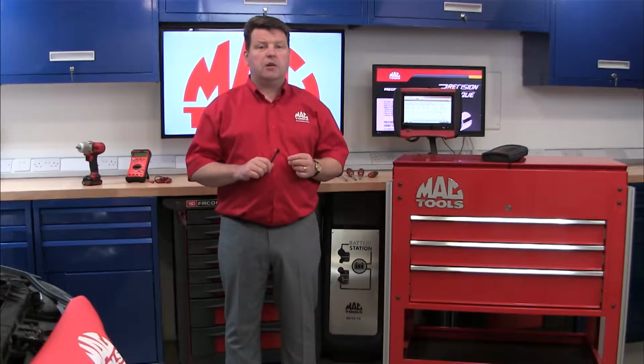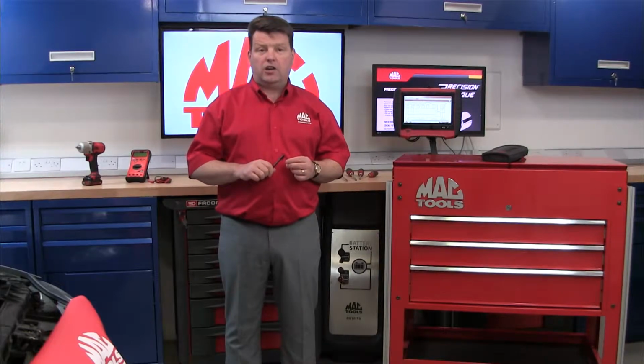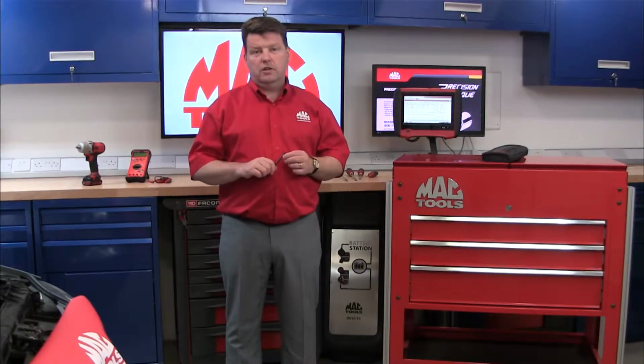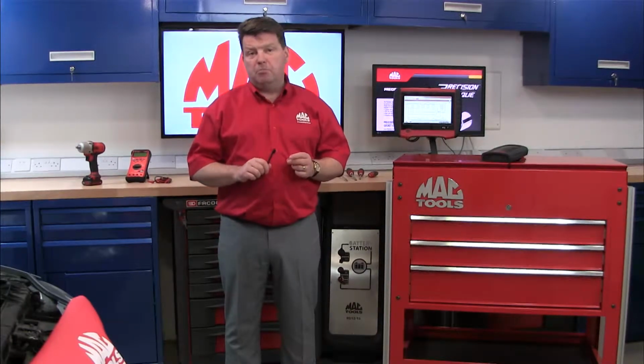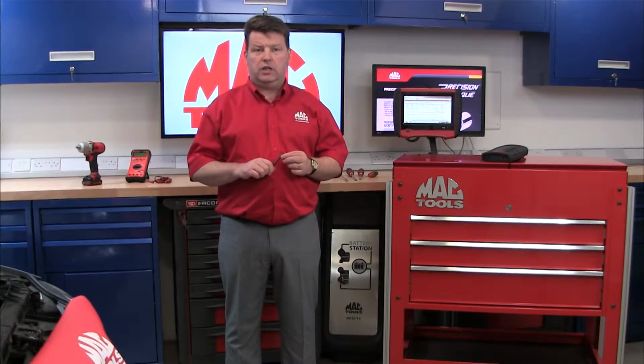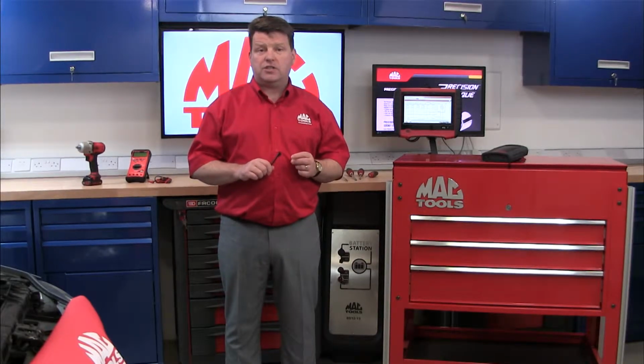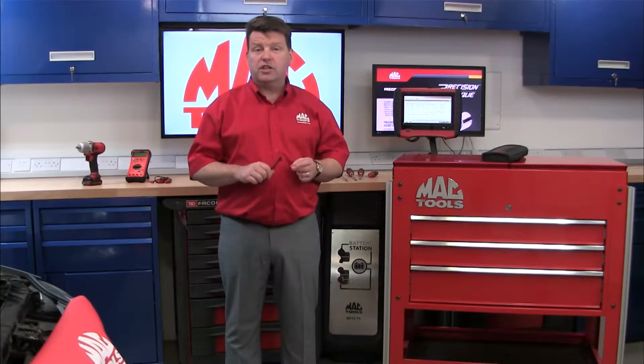This is just an example of how being able to interpret a wiring diagram will enable you to ask better diagnostic questions. From there, you can do the most important part of any diagnostic routine, which is to carry out the tests and keep on testing until you find the fault.